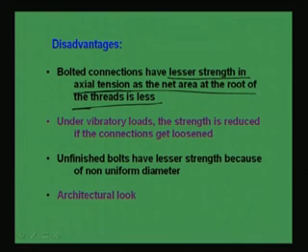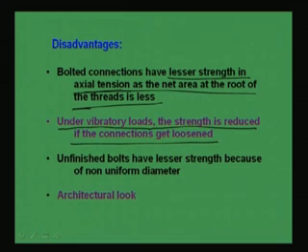Another, which is very important, is that under vibratory loads the strength is reduced if the connections get loosened. Because of vibration the connection may loosen, so the strength will be lost. So in case of vibration, generally we avoid bolting connections, because chances of loosening will be there unless it is tightened properly. Another is that unfinished bolts have lesser strength because of non-uniform diameter.